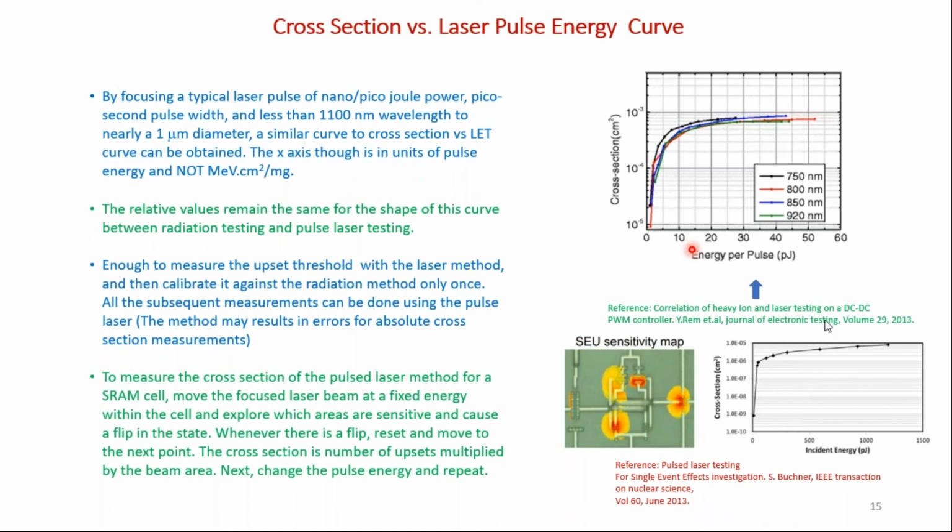Thank you. Yes, especially if you want to use it for identifying the error modes that you get, right? Because your time in the accelerator is pretty limited. You may stay there for a few days and you're spending thousands of dollars per hour to do the test. So rather than identifying the errors there, you could use something cheaper and more efficient that gives you spatial resolution and temporal resolution. Identify all the errors first, and even disqualify some of the components that you'd be taking there. If you're testing 100 components, you could quickly disqualify some of them before you take them. This way you reduce the amount of hours you spend in the accelerator. Does it make sense? Yeah, it does. Okay, great.